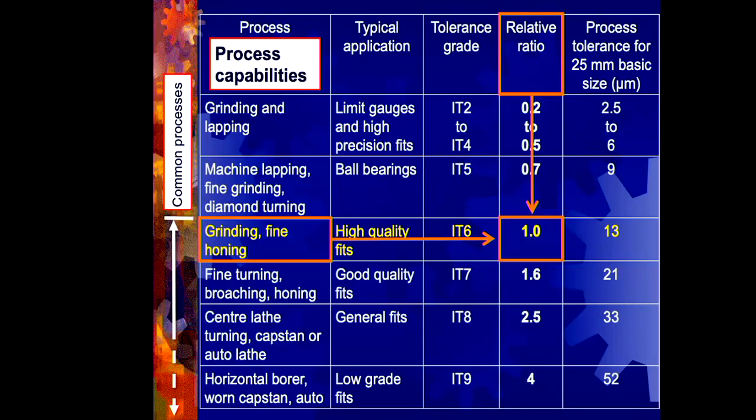But this chart, I hope, is indicating to you that trying to have a tolerance on any object, a smaller rectangle height than, say, 2.5 microns, to be blunt, would be goofy. I'm just showing you that very, very precise and expensive manufacturing processes get us down to about 2.5 micron. What is the application that you might assert needs to have a higher or tighter tolerance?